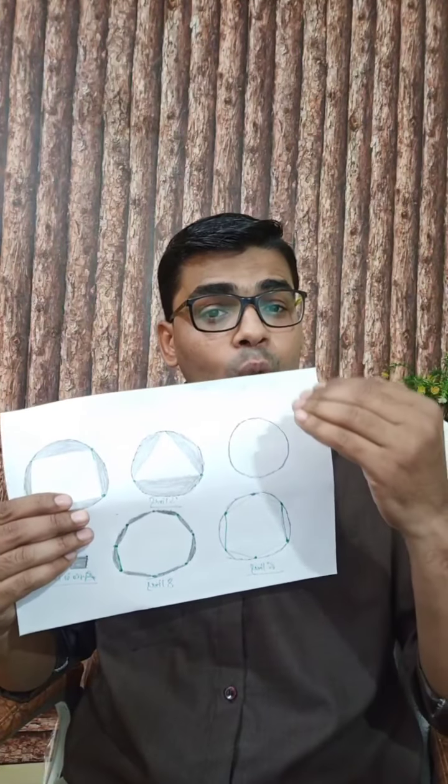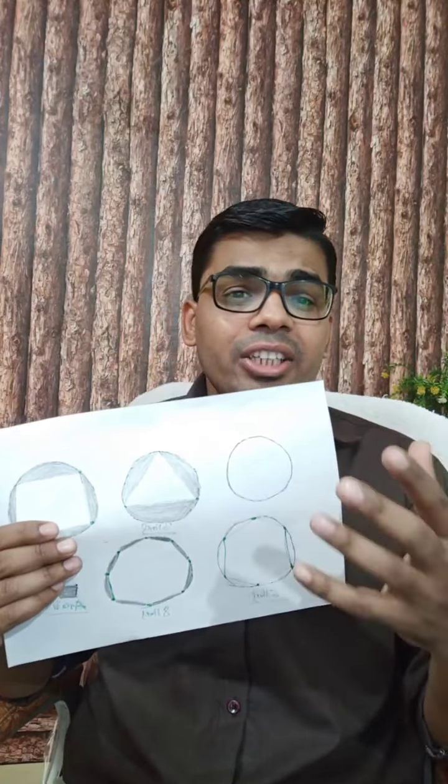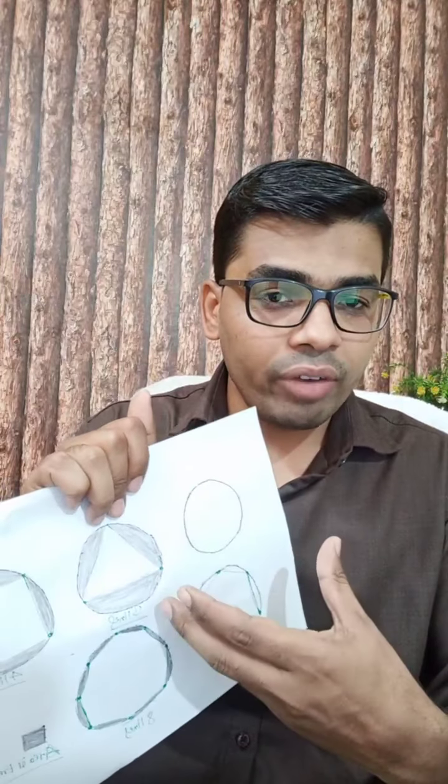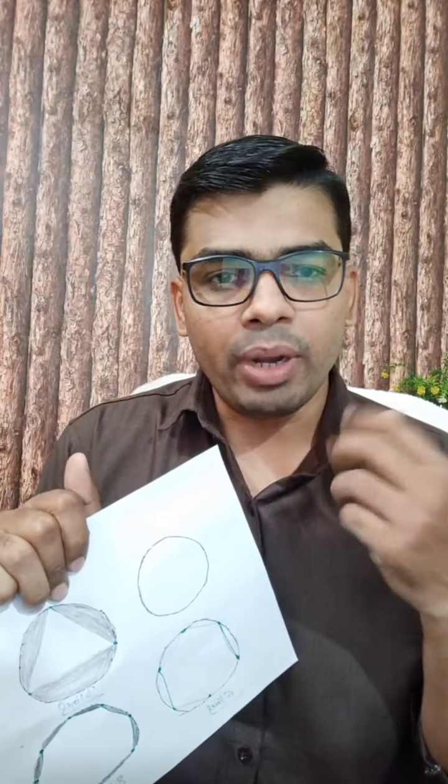Yes, up to 80 to 90 percent it is considerable, depending on how much time you have spent and depending on the design phase you are involved in. For example, if you are involved in conceptual level design simulation, then you can go with a coarse mesh and identify where the hot spots are coming, and later you can go for a fine mesh at that particular area and simulate the problem.